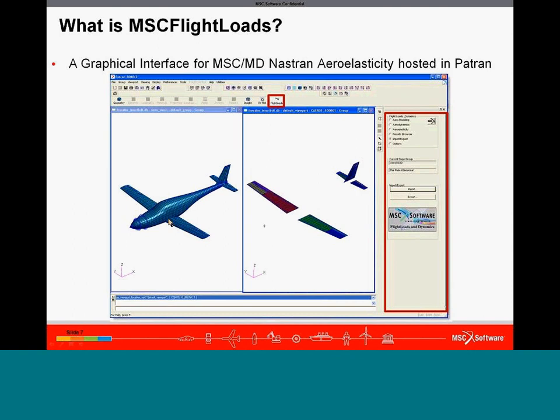It does have an ability to import the general Nastran 3D aero mesh. If any of you have looked in the recent release of Nastran, there are the AE Quad and AE Tria type general 3D surfaces that some customers are using to bring in displacements for CFD, etc. So it can import that as well, although we're just going to focus on doublet lattice today.